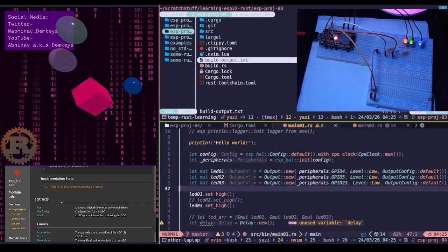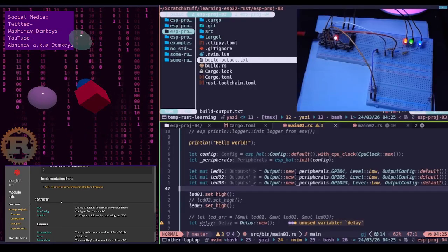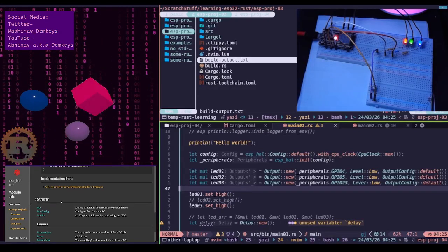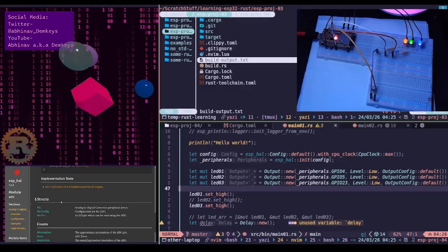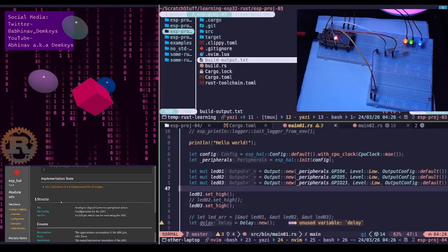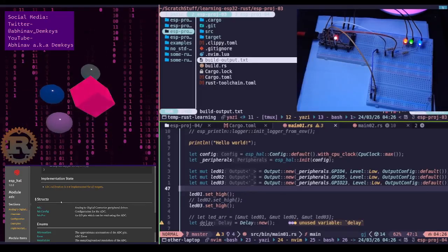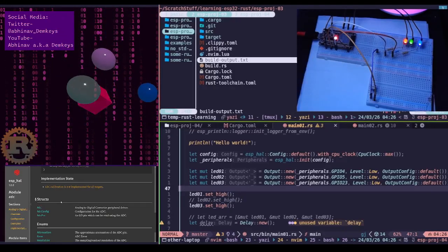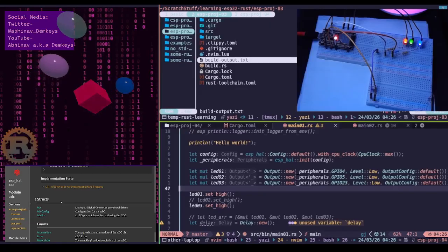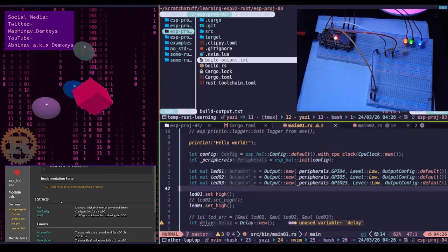Yeah, that's true. I do have that extra resistor even now. Even when I've turned the trim pot all the way down, the LED isn't completely bright because there's a tiny bit of resistance in there. About probably 270 ohms of resistance is still in there. Also, I'm not entirely sure if the pot's zero resistance is actually zero resistance. I feel like I should look into that. Is there still a small amount of resistance being applied there? But okay.